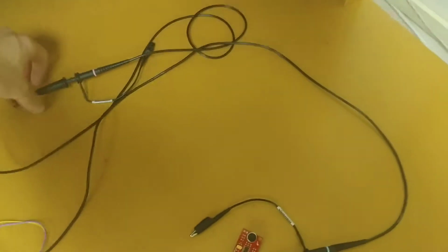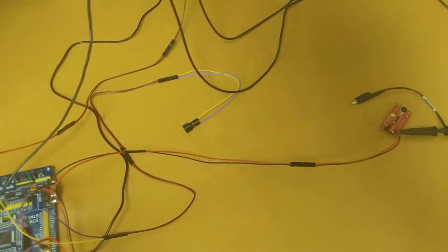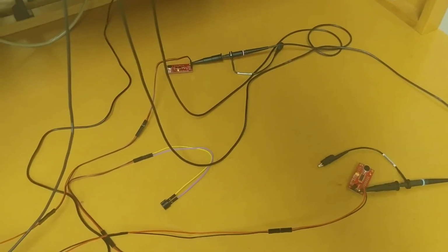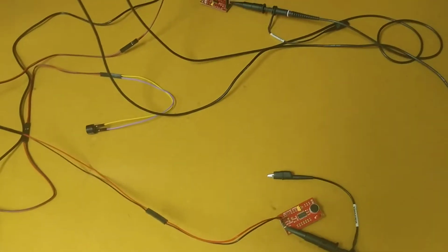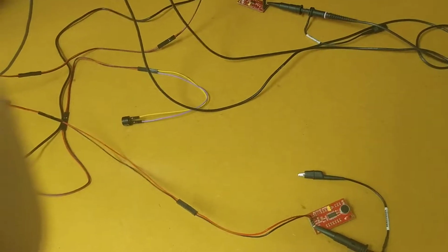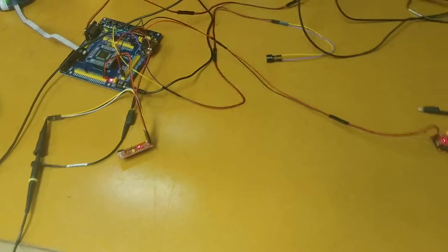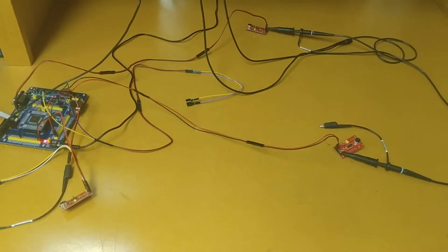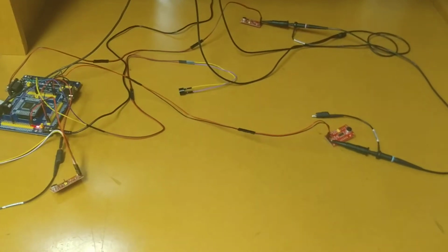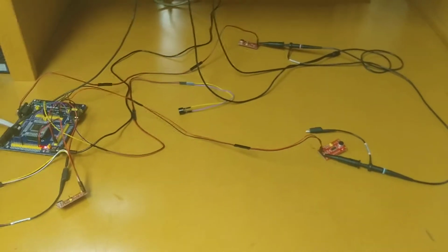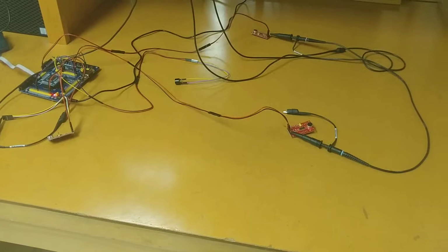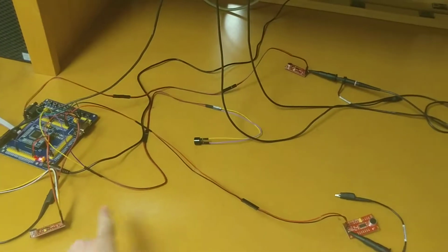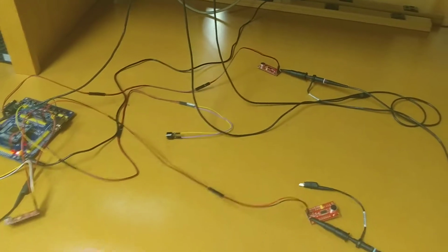Let's actually turn this thing around here. You can see that the LED on the actual board powers simultaneously, indicating that it is actually picking up the same sound. So theoretically, the difference in time of arrival when these three are recorded simultaneously should allow us to triangulate the actual source of the sound, basically just using the actual distance between all of them. Or actually, I think that the term is trilaterate.